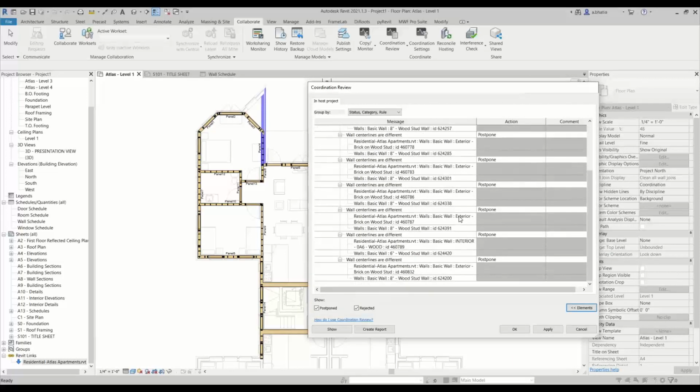And for your question about if you have walls pre-drawn, typically Revit copy monitor is meant for, instead of you sketching it manually and drawing it perfectly to the exact dimension, copy monitor kind of just helps you copy the walls from the linked file, right? Right. But if you do want to go ahead and copy monitor, you can definitely do that. I do know I've done that in the past when I was working for a structural consultancy. The architect changed way too many walls.